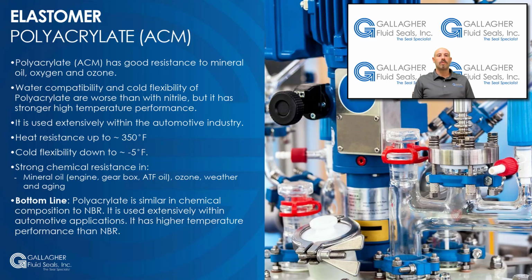And finally, we will discuss polyacrylate, or ACM, which has good resistance to mineral oil, oxygen, and ozone. Water compatibility and cold flexibility of polyacrylate are significantly worse than nitrile, but it has stronger high temperature performance compared to nitrile. This material is used extensively within the automotive industry. Polyacrylate offers heat resistance up to approximately 350 degrees Fahrenheit and cold flexibility down to approximately -5 degrees Fahrenheit.